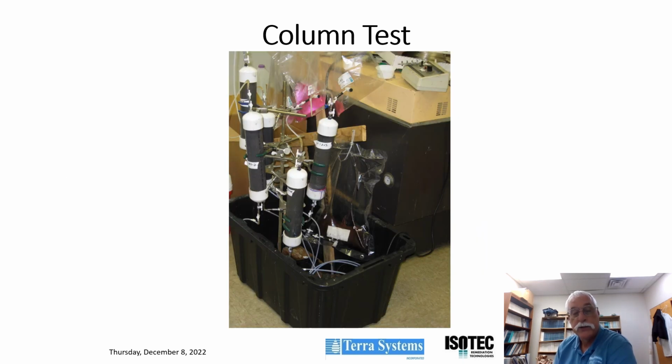So this just shows a picture of the columns. You see the 12-inch columns collecting our influent samples, and the effluent samples were collected in Tedlar bags to control the amount of oxygen infiltration and to collect the volatiles and dissolved gases for analyses.